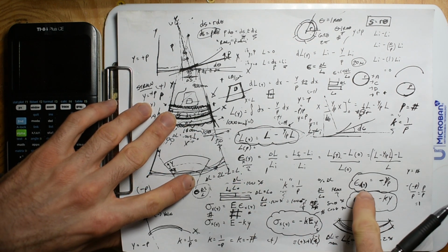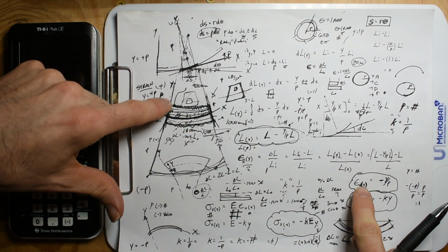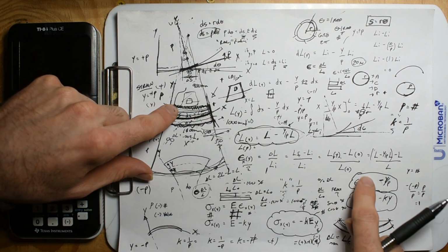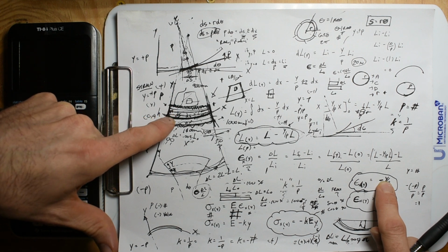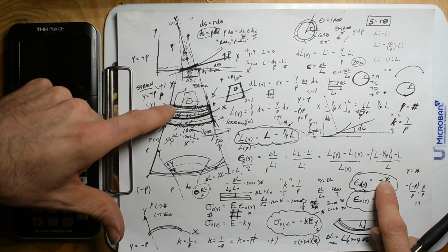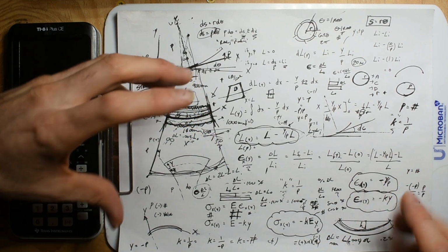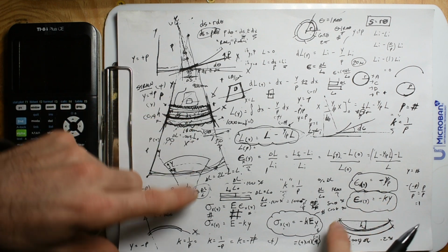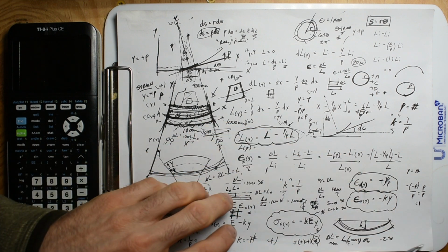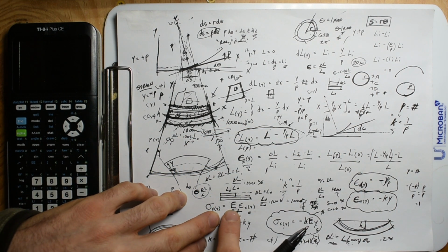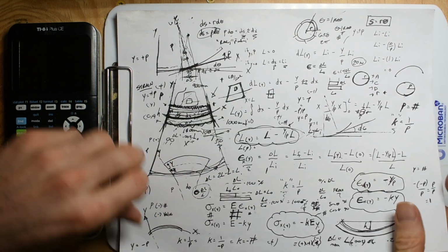I was thinking, hey, if we know the strain, we know the force as well. But this strain, we're using geometry to find the change in length. So this strain component, this equation, is our input value of where we are on that beam. If I'm up at the outer reaches, my strain is going to be the largest. My change in length is going to be the largest, and this equation says that's related to the force, the internal forces. So stress is related to strain just by a constant, because we set up tests and find that slope. All right.